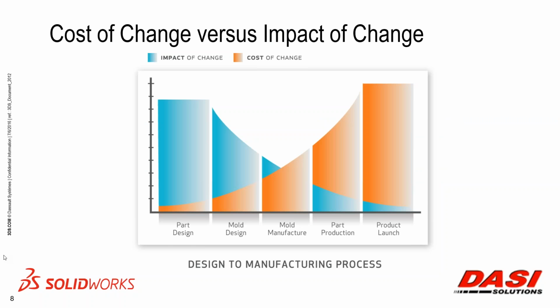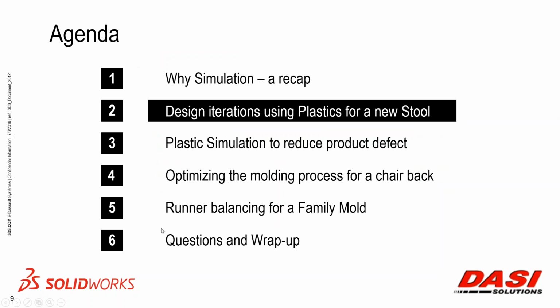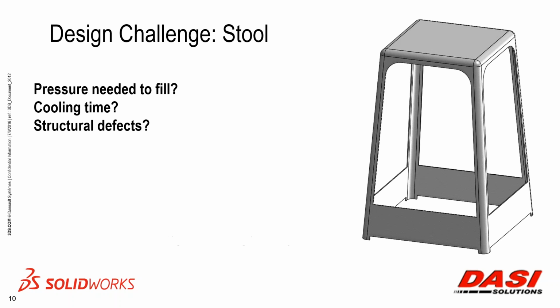Okay, great. Thanks, Dave. All right, so the first hands-on model I'd like to look at with you is a stool. You can take a look at the initial design on the right of this slide. It's a bit crude to start with, but we're going to figure out: is this thing going to fill? How much pressure is needed if it does fill? How much cooling time does it need? It's rather thick right now. And then we'll take a look at whether there are any structural defects.